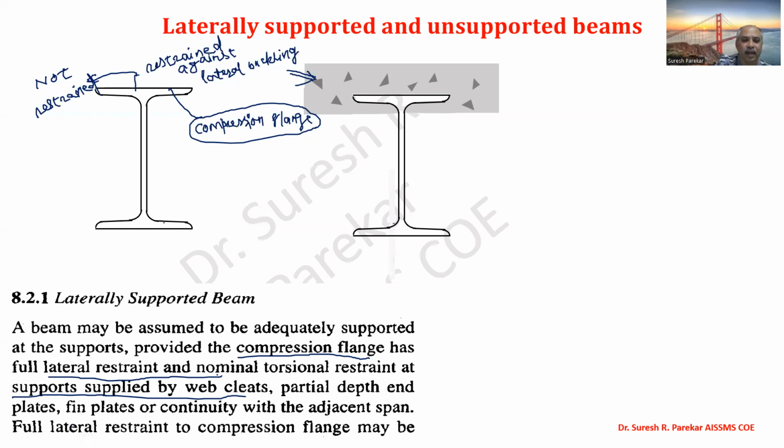So that is full lateral restraint to the compression flange, and we say full strength in this case. So this diagram is laterally unsupported and this is laterally supported.